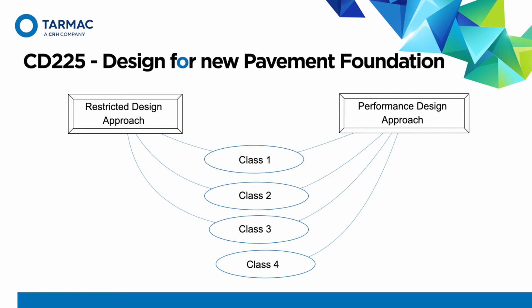Also, as we know, there are different classes of the foundation, class 1 to 4, based on the surface modulus: class 1 being above 50 MPa, class 2 above 100 MPa, class 3 above 200, and then class 4 above 400.